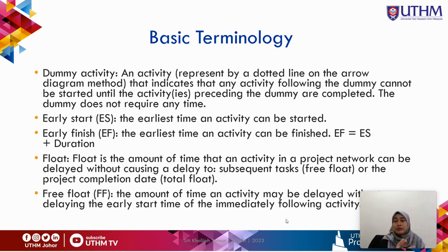This is represented by a dotted line on the arrow diagram method, and it indicates that any activity following the dummy cannot be started until the activities preceding the dummy are completed. So this is just an arrow that shows the relationship of one activity to the other activity's completion. If you're using ADM and you use a dummy in your network, the dummy doesn't have any time. It just shows the relationship.